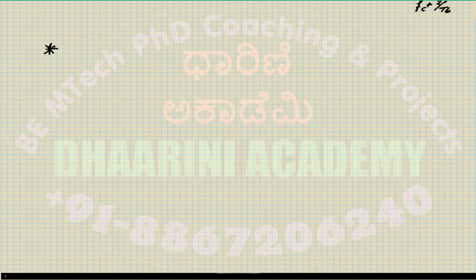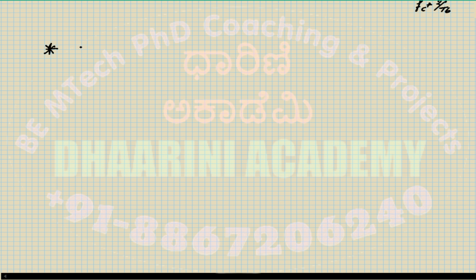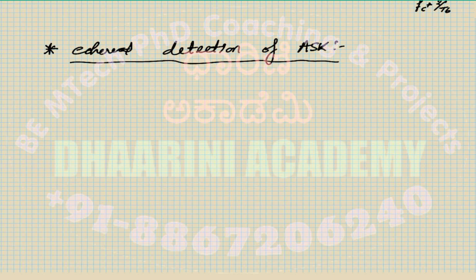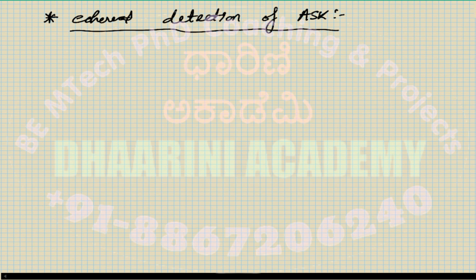The word coherent comes not because of the modulation technique, it is because of the demodulation technique. The demodulator knows what the frequency is. So this is the coherent detection of ASK. Coherent detection, as the name suggests, means you know the frequency of the carrier. So let's directly write a block diagram. The block diagram itself is sufficient to understand the whole concept.